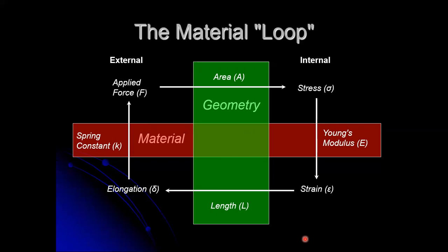When we use it for design, we sometimes bring in what the material is and what we expect the stresses to be, and we try to figure out how small we can make the member so that it maxes out the stress, or gives us some small amount below the maximum stress so we can be as efficient as possible. So we mess with the order a lot to figure out what's going to work best.